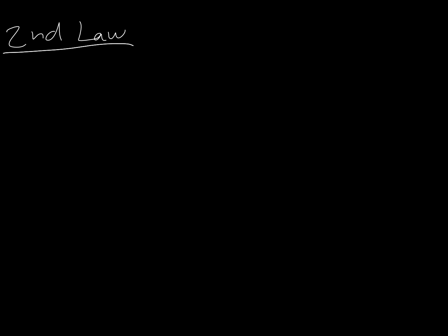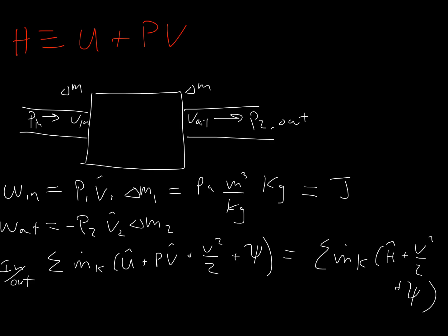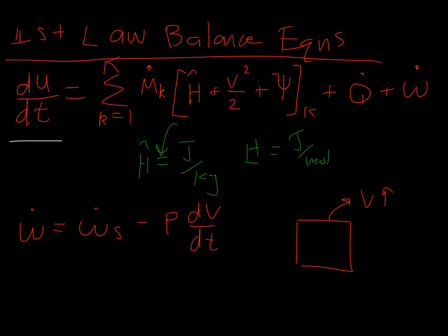Yeah, so let's rehash that a little bit. The W dot term here, let's talk about this expression down here. The shaft work is like if you're extracting energy from a turbine, for example. You bring in superheated steam and it leaves saturated steam, right? Which, for example, is one of the homework questions. How much work can you get out of the system?